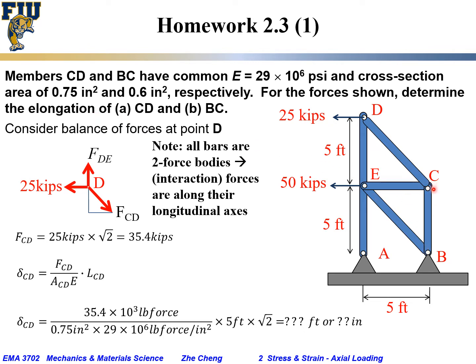Again, this is not statics, because in statics you would consider these to be rigid bodies and the elongation would be 0. But in this class they are not 0. And we have Hooke's law that they expand linearly when the stress level is low. Okay, so let's first consider the CD rod.